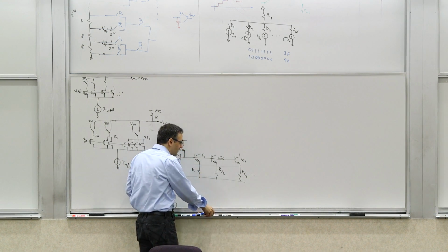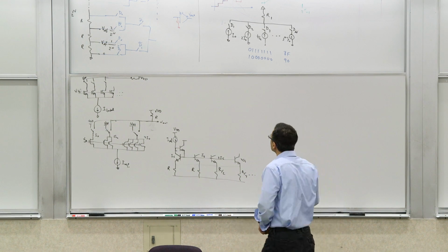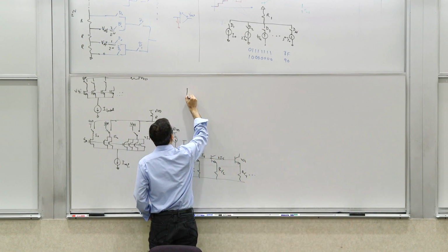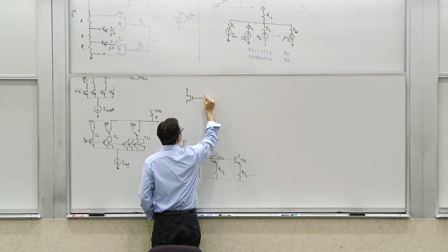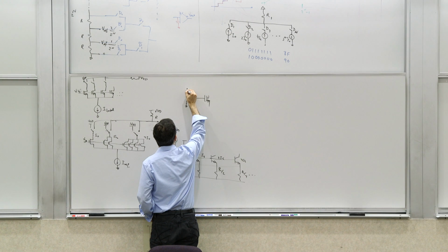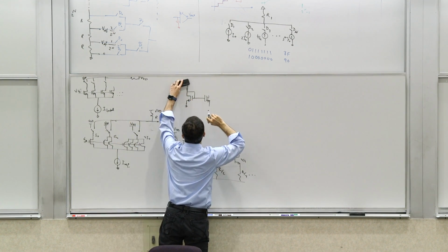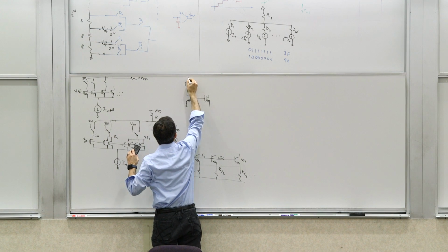That's fine. Now, how about MOSFETs? If you wanted to make multiple branches with MOSFETs, you could do it this way, in a similar fashion. You don't have the thermal runaway issue or the gate current issue in the case of a MOSFET, or at least the traditional MOSFET.